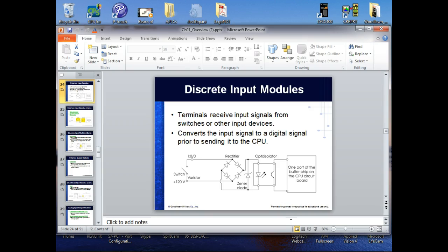Yeah, instead of coming back and pulling in a whole new cable, which is real hard, you can switch over. So the technique is to get more input ports than you need and more output ports than you need. So if you blow up one of your input ports, then what could you do? You could switch over, and you'd have to go back and make corrections, but that wouldn't take that long.